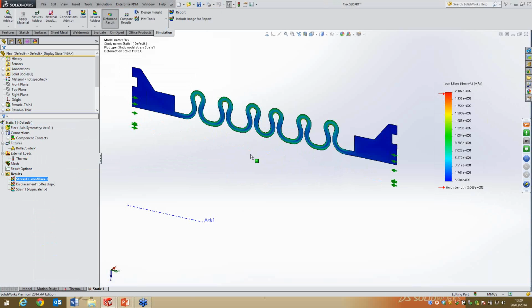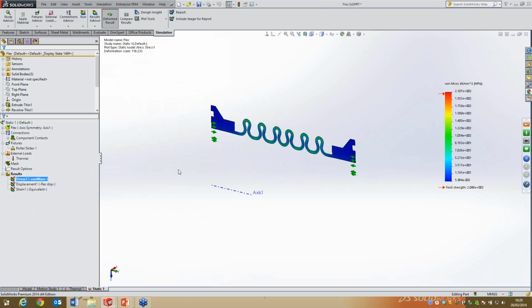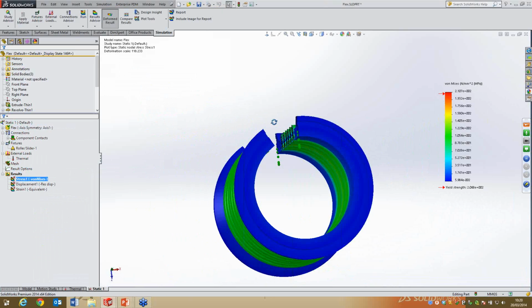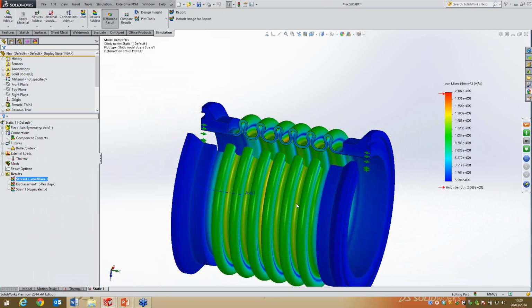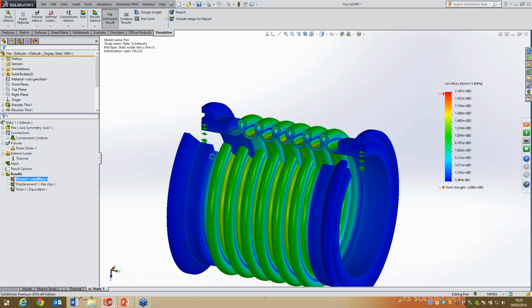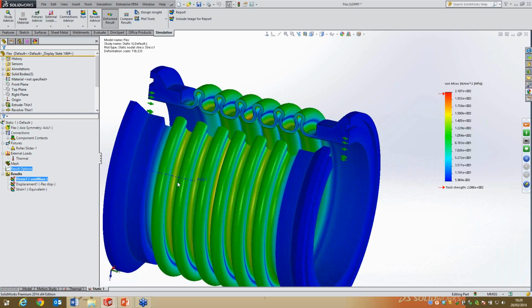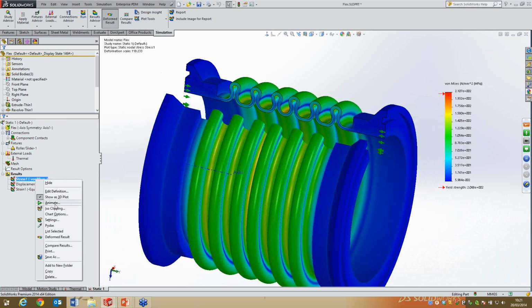What you can do is when you get these 2D studies, as I said before, once you actually click on the plot and have it activated, you can right click and go show as a 3D plot, and it does a nice 3D plot and then leaves you a nice section on one side. So you can see here it looks almost identical to the, well, it is identical to the initial geometry we started with. So if I go ahead and animate this now,